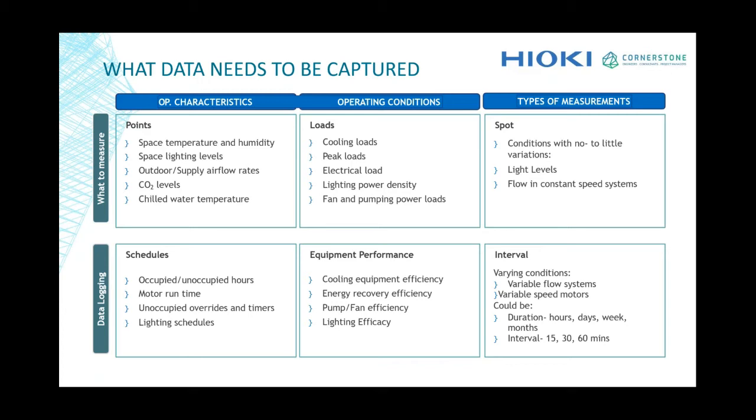If you look at lighting, we have what are the lighting levels. So we measure the lux levels and things like that. Focusing on the air handling unit and FAHUs, especially for fresh air handling units, we would look at what are the CO2 levels. So looking at the air quality side, that measurement will be done.